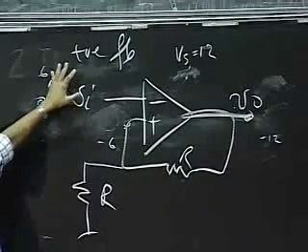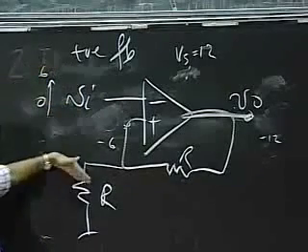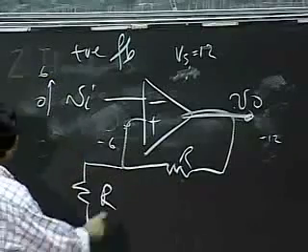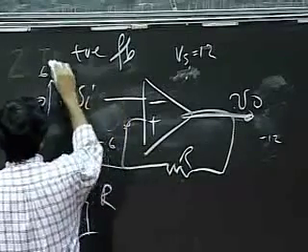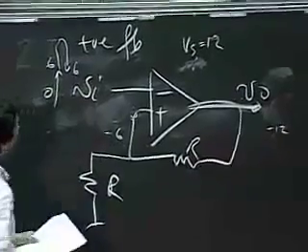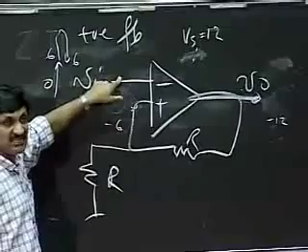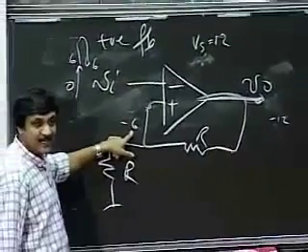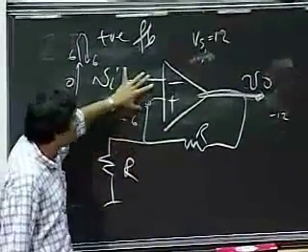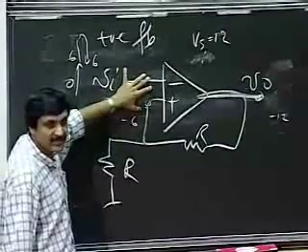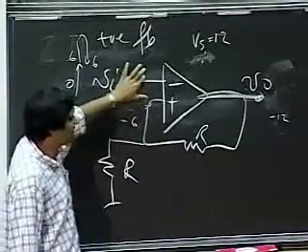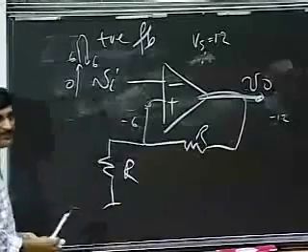Okay, so I'm pretty safe. Then let's say V begins to come down. As V begins to come down, does anything happen when V gets to 6 again? If V is equal to 6, what happens? Nothing, because this is at minus 6 now. Okay, so there is still a huge net negative voltage here, from V plus to V minus, and therefore I sit at minus 12.